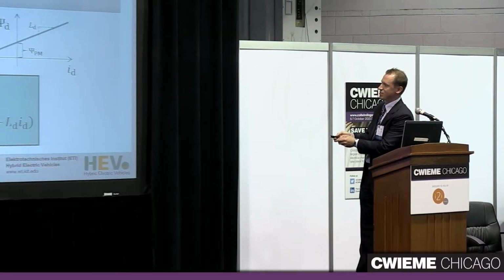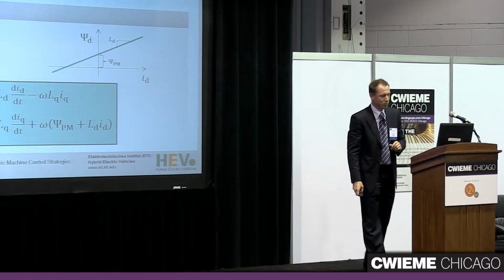And what we then do normally, at least with our students, we say, well, our machine is linear. We have linear magnetics. And that means that the flux linkages depend linearly on the currents, as given by the equations here, or like this sketch. This is just a straight line. That means linear magnetics. If the current is 0, you still have some flux linkage left. This is the permanent magnet flux linkage. You can just put that into these equations, and you end up with the linear system equations that some of you probably know.